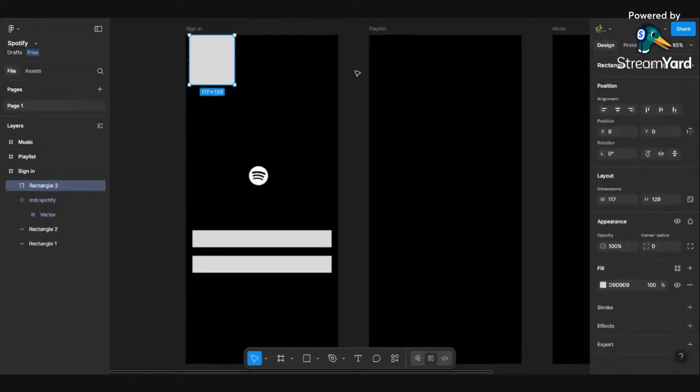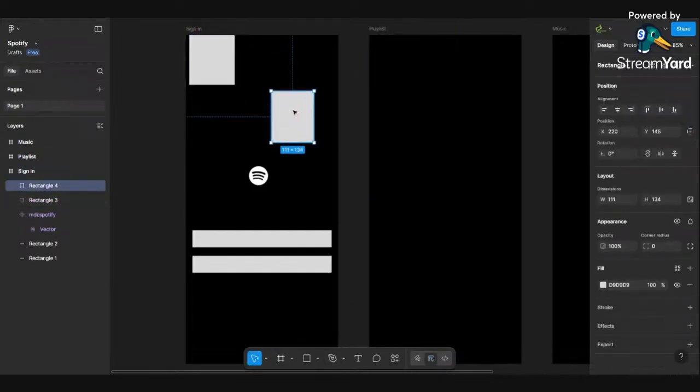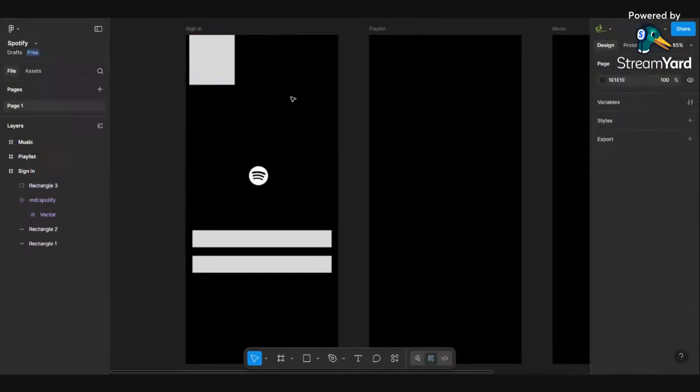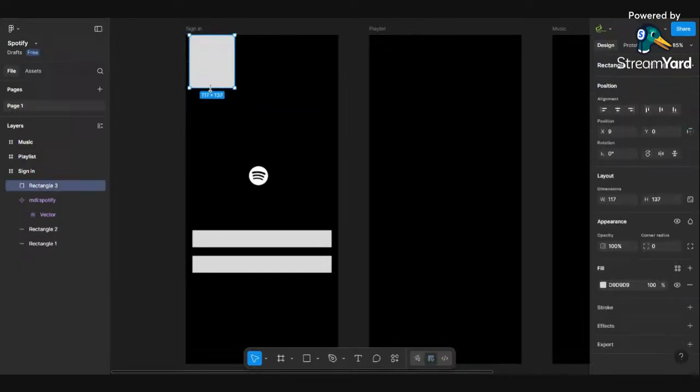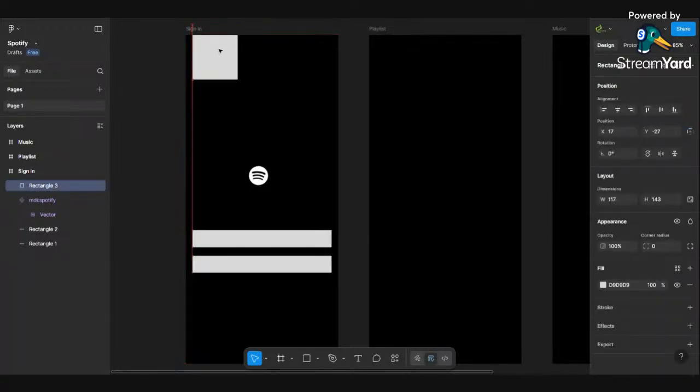I suggest you don't make so many boxes like this, so the dimensions will be the same. Make one box, make it something like this, and place it here. And do what I said: press Alt, and you can drag it here, and make sure it lies exactly below that existing box.